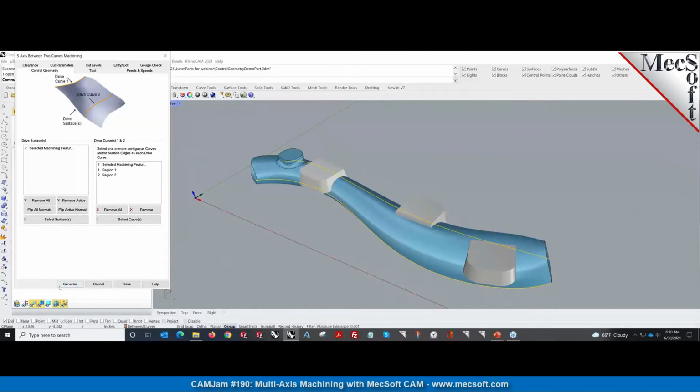The drive surface in 5-axis mode, as compared to the 3-axis mode, there are two things associated with the cut pattern. In 3-axis, when you said parallel finishing, you would say basically take parallel planes along the X or the Y axis or any angle axis, and then basically slice the model, and wherever the model is sliced is where you're cutting.